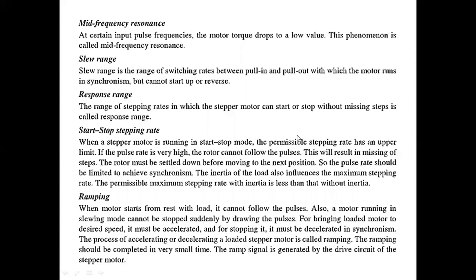Next one, you also have to observe start-stop stepping rate and ramping. When the motor starts from rest with load, it cannot follow the pulses. Also, a motor running in slewing mode cannot be stopped suddenly by dropping the pulses. For bringing a loaded motor to desired speed, it must be accelerated, and likewise for stopping it. But all these are considered under loaded condition, not only off-load condition. These all are considered under on-load condition.